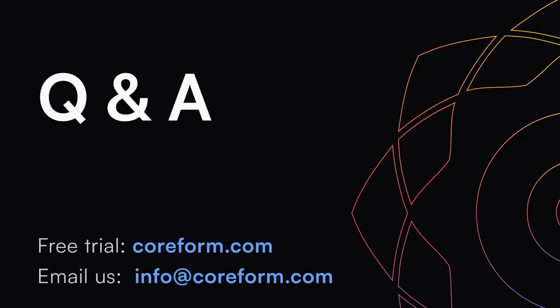Okay, let's see. Go ahead, Greg. And I will say too that we're really excited about these methods in explicit, because as you increase degree, your stable time step actually goes up rather than goes down. So a lot of the issues that have maybe plagued higher order elements for explicit dynamics are resolved by these IGA methods. We're very excited about the prospects of IGA for explicit analyses.